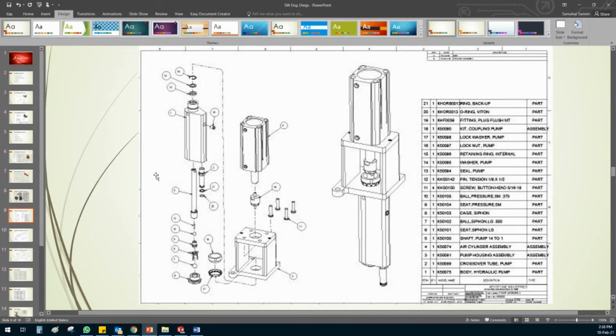But the bill of material can be very detailed also. It can have weight, material, size, quantity, how many you need, how it fits, where to get it from, and how much the price is. So the bill of material can be as detailed as you want. But briefly, on the drawing, we don't put so much detail. We put only what part number 1 is, and how much quantity you need.